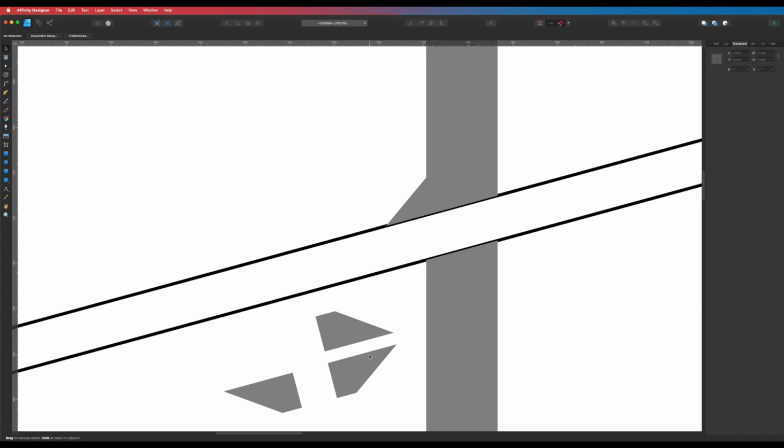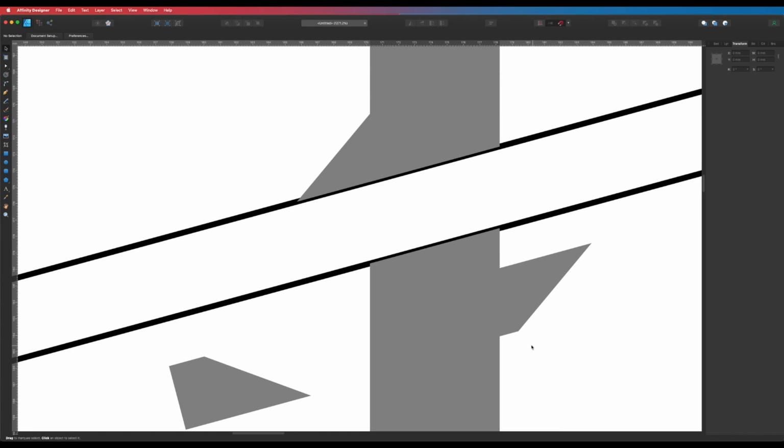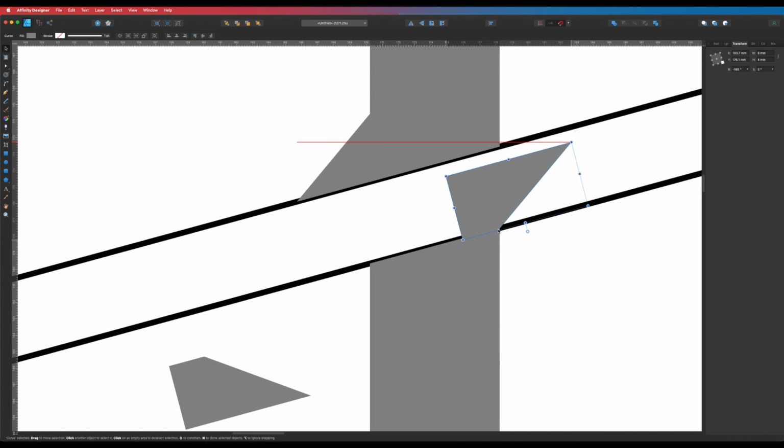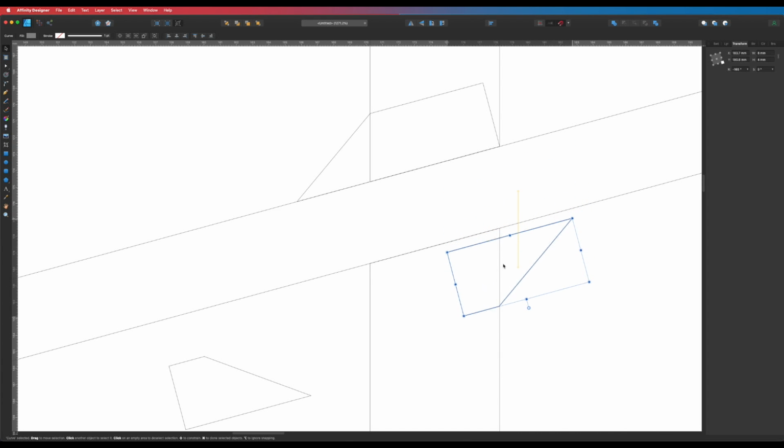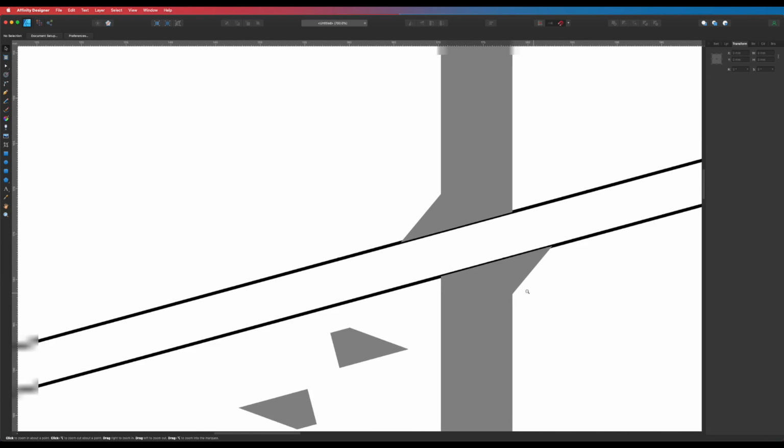Now we need one facing the other direction, so that's this guy over here. Click and drag him. I'm going to drag him right to this little edge over there, right to that corner. Go into your wireframe mode, let's drop him down. Okay, just get them perfectly in there, as perfect as you can. Okay, so those lines align. Click the graphic, hit A. I'm going to select this node over here and this node over here, click and drag them, snap it to there. Command Y, and that's what we're looking for.